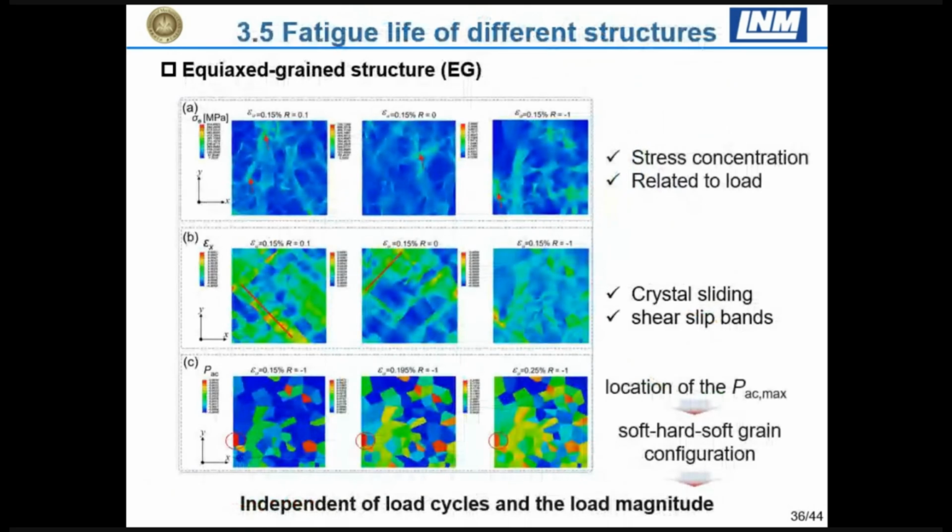And another thing we need to consider is that in our microstructure, equiaxed and columnar grains both exist. But if we do some heat treatment, maybe only equiaxed grain microstructure will exist. So a question is raised whether this one has a higher fatigue lifetime. That would demonstrate that heat treatment is very good for additive manufacturing. So in this sense, we compare fatigue lifetime with different microstructures here.